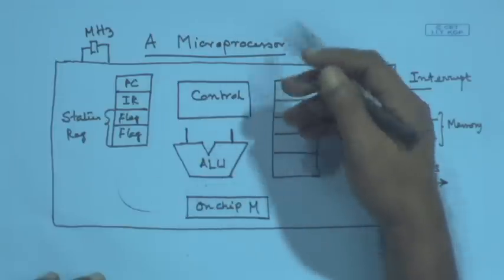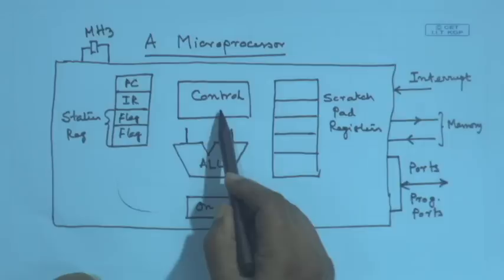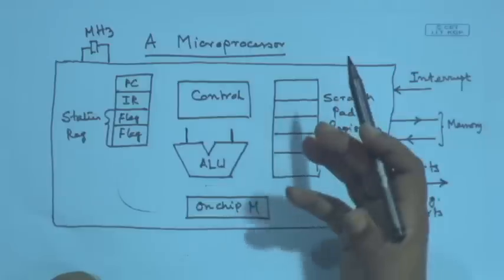registers or with the other lines. Now, for the different instructions, there should be different paths that will be activated during execution, and that activation is being done by the controller. So, the controller, as we discussed, is essentially a state machine which is in the present state. Depending on some inputs, it goes to the next state, like that it goes on.